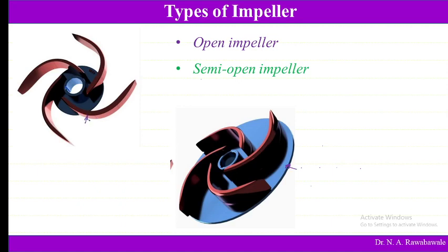So what is the difference? If the impeller is completely open, back leakages are going to happen, and that is going to reduce the head and cause a loss of energy. The desired head cannot be attained and the efficiency of the pump gets reduced. So to improve efficiency, semi-open impellers were introduced. Thereafter they introduced the closed impellers.